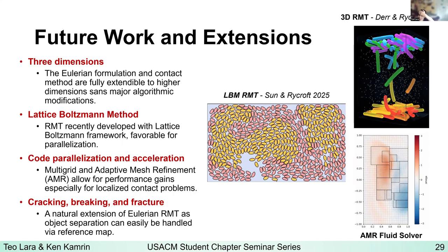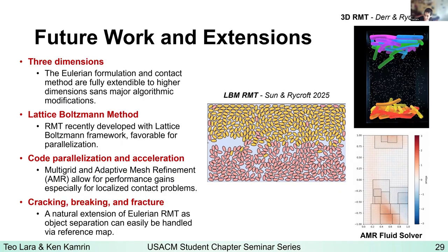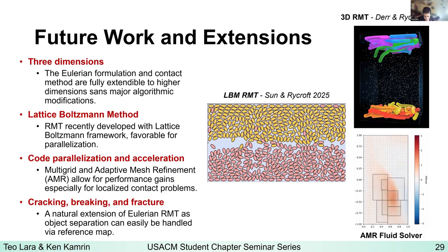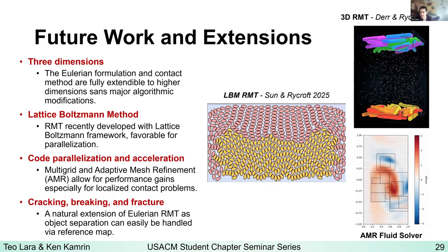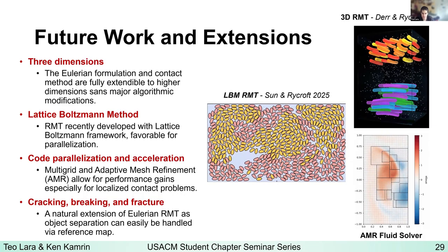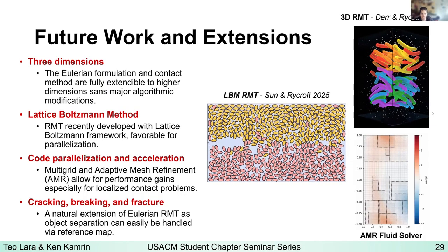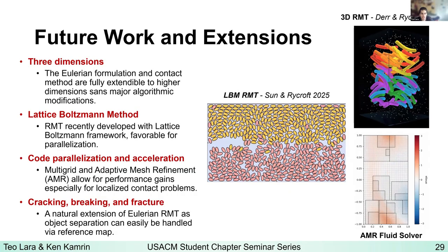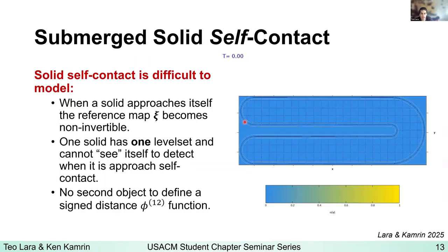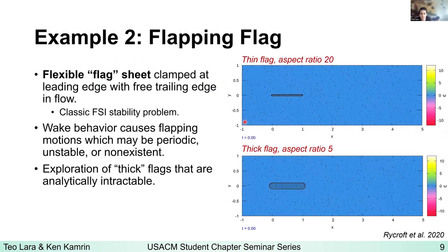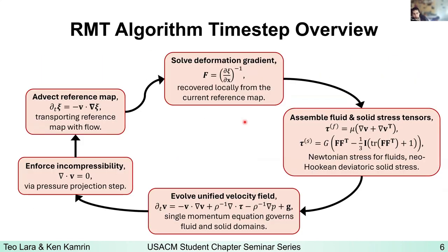Generally, yes. Very likely, yes. The reference map technique already separates the kinematics from the constitutive law that is happening, right? All you have to do is plug in your new stress back in one of these equations here. Way back here, you just plugged in your stress strain relationship.